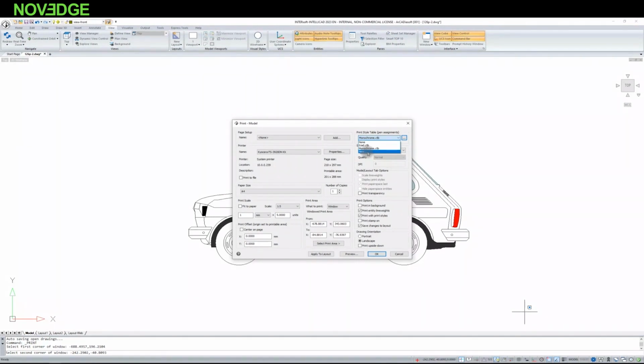You can save such a template in your document. To find the place where you save, go to the Windows Explorer window. There you have main Windows documents. There is an ArCADiasoft directory, and here there's an IntelliCAD directory. And that's exactly where your templates are. And if you get any template from outside, please copy it into this location.